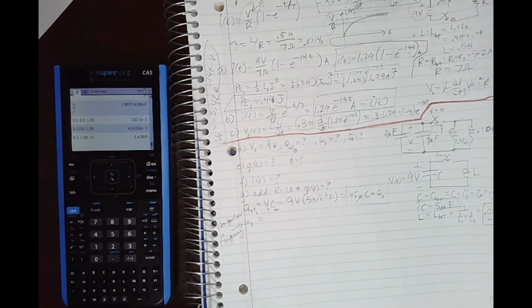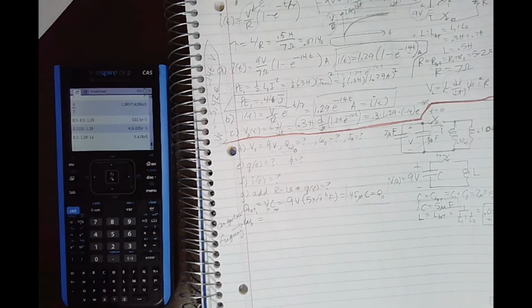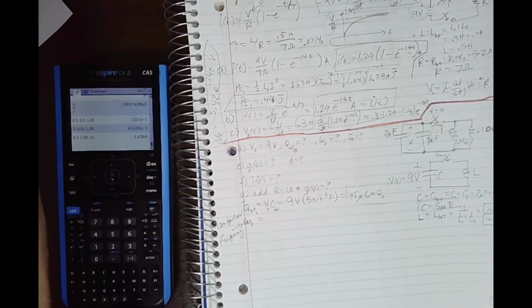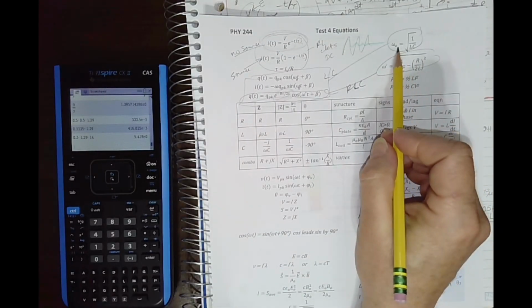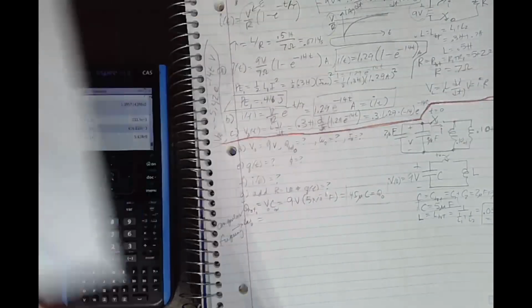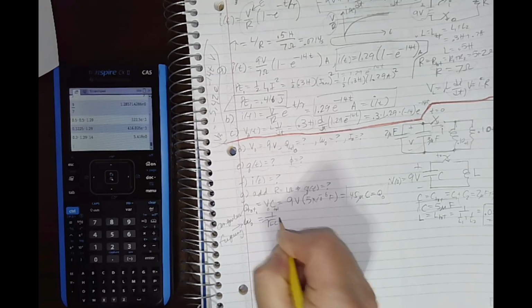So omega is our rotational speed, but in our cosine circuits it's the angular frequency, 2 pi f. But we have an equation for this. For an LC circuit, just a simple L and C with nothing else in it, we call the natural frequency omega naught, which is 1 over the square root of LC.